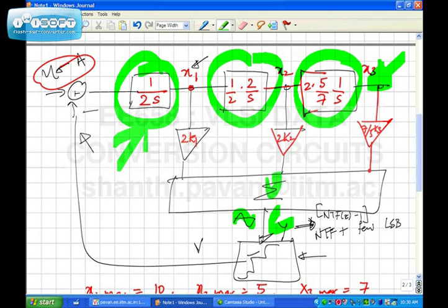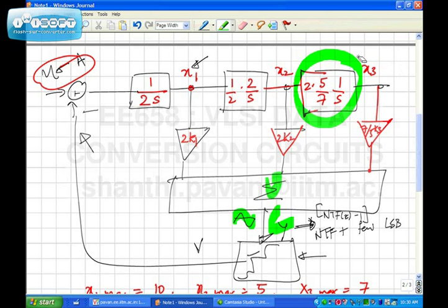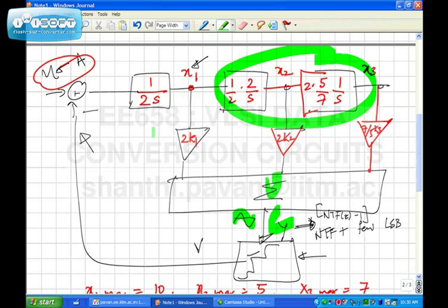Whereas here swing is not that important. So in principle, you would definitely use at least 2 types of op amps. One for these two guys and one for this guy. Pardon? Oh, well, see, this op amp will swing the largest, correct? Whereas the noise requirements of these two integrators is very less. For those of you who don't understand noise, never mind. The noise requirements of these two guys are very less. So in other words, the impedance levels of the R used for these integrators can be much larger. The power burnt in these op amps can be much smaller.